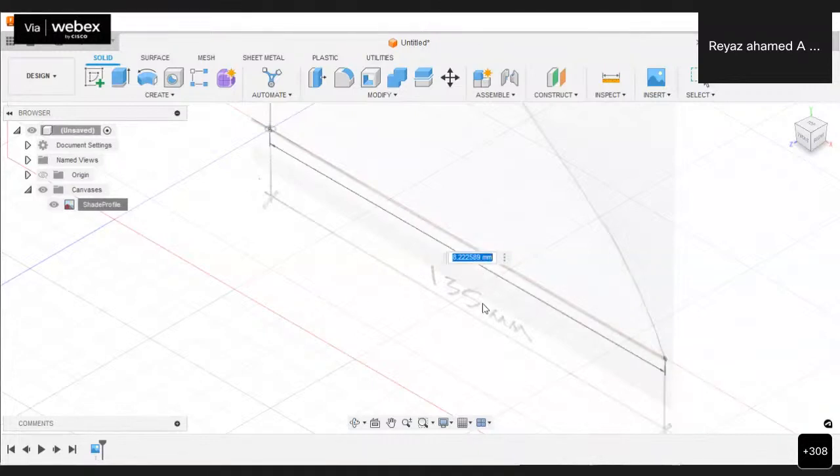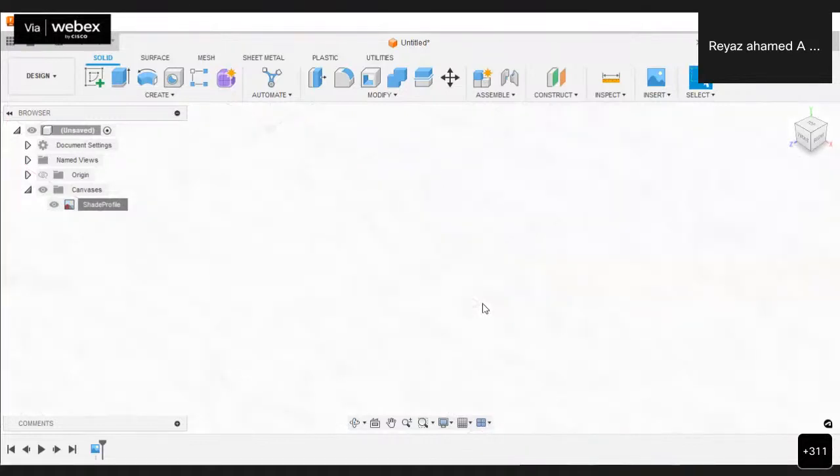See the dimension now. It is 8.2222589 mm actually. So only 8 mm is there. But actually what we needed is that the image should have a base of 135 mm. So we have to convert this image into 135 mm. So just edit this 8.22 to 135. Edit that value 8 to 135 and then click on enter. See the image is not there because the image automatically gets scaled up actually. So let me bring into the home view again. Let me click on the home button.